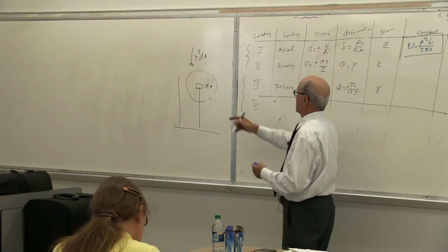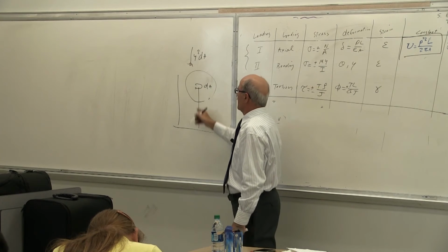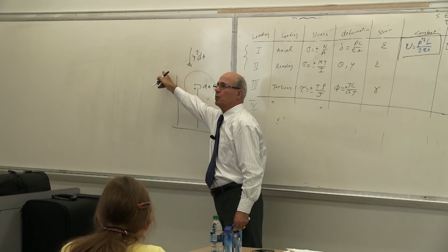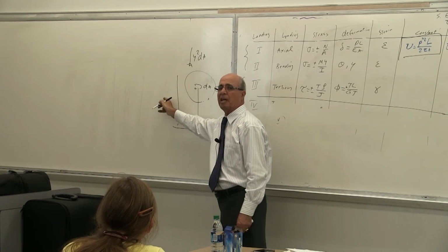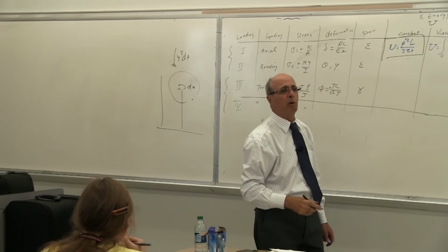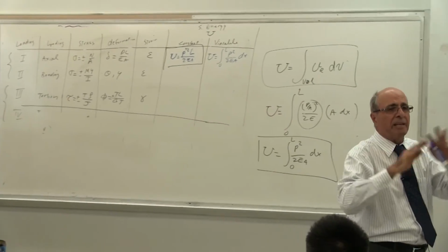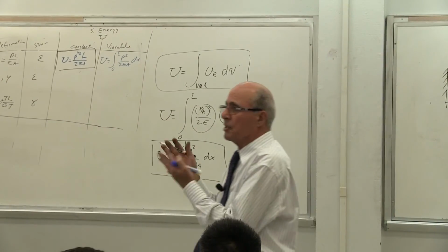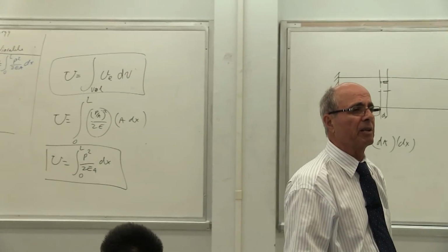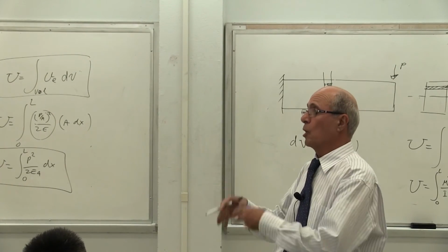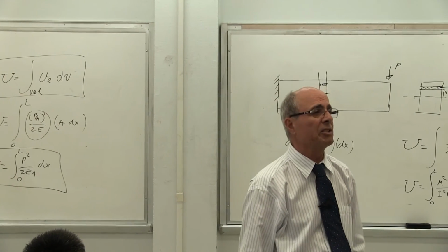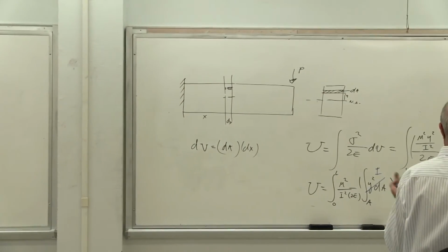All you need for the 2 chapters in statics, centroid and moment of inertia: dA y is Qx, dA x is Qy, dA y prime squared is Ix, dA x prime squared is Iy, and dA rho squared is polar moment of inertia. That's it. That's the entire 2 chapters, but it is that simple if you go based on the idea. The rest is formulation. Is that correct or not? You have to use that integration to get the moment of inertia for a rectangular shape, which ends up being 1/12 of base times height cubed. So that is the principle.